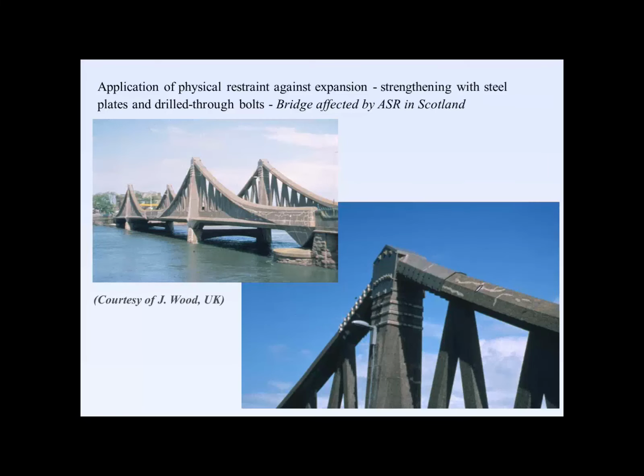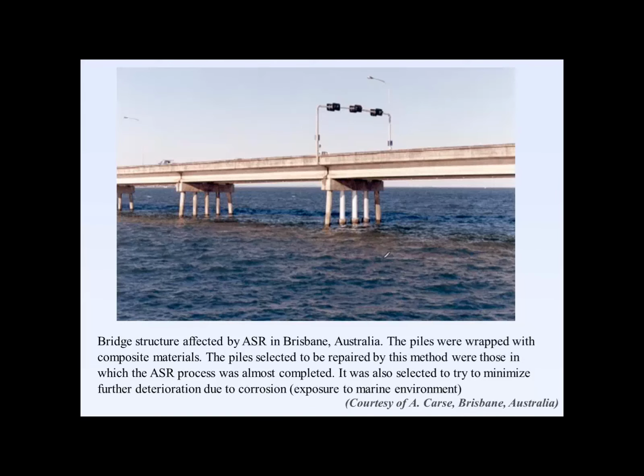This external restraint is not only limited to footings or foundations, like I've shown here, but it's also been applied to bridges as well. Here's a case where an arch bridge was retrofitted in Scotland through the use of steel plates and drilled-through bolts. And you can see here where that repair was done. This was both to try to mediate the ASR itself, but also to restore the structural integrity to this sensitive arch dam that you see.